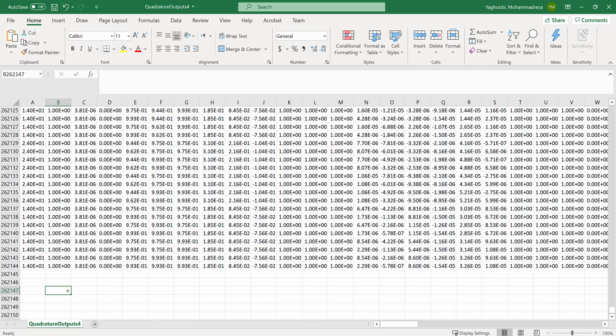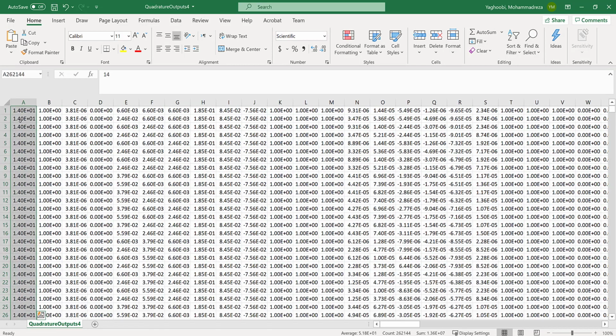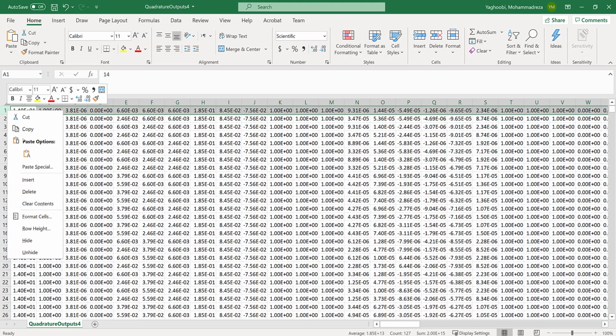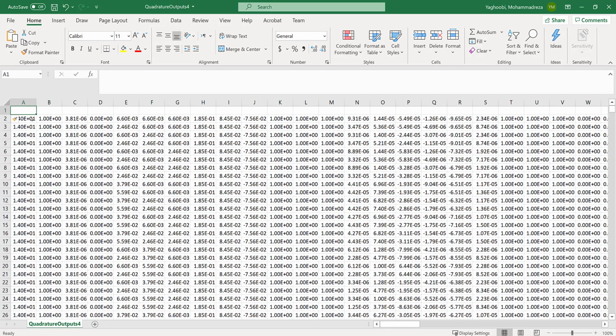But what information do we include here? What I typically do is add here and write one by one what each of these columns means. The first one is the grain ID for that integration point. The next one is the phase if you have multi-phase, otherwise it will be 1 for all the integration points. Be careful, if you're using the advanced twin model, this column will be deleted. The next column will be the determinant of the Jacobian for that integration point.